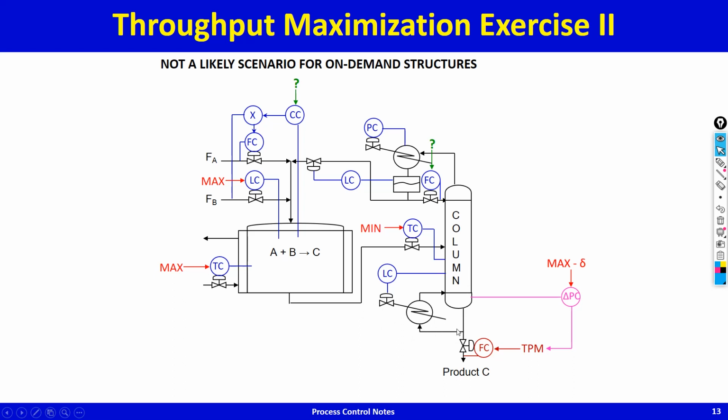So the variability in the boil up is sort of not immediate, but the dynamics is not very slow. Because the dynamics is reasonably fast, you could have reasonably tight control, and because you have reasonably tight control of delta P using this magenta loop, therefore the backup is not going to be large. There's going to be some backup, but it is going to be much lower compared to the previous control structure.